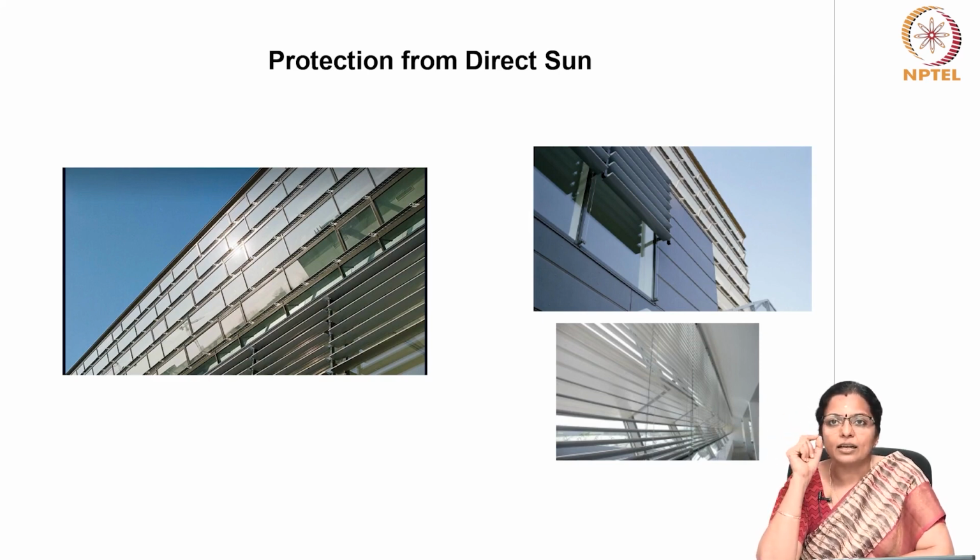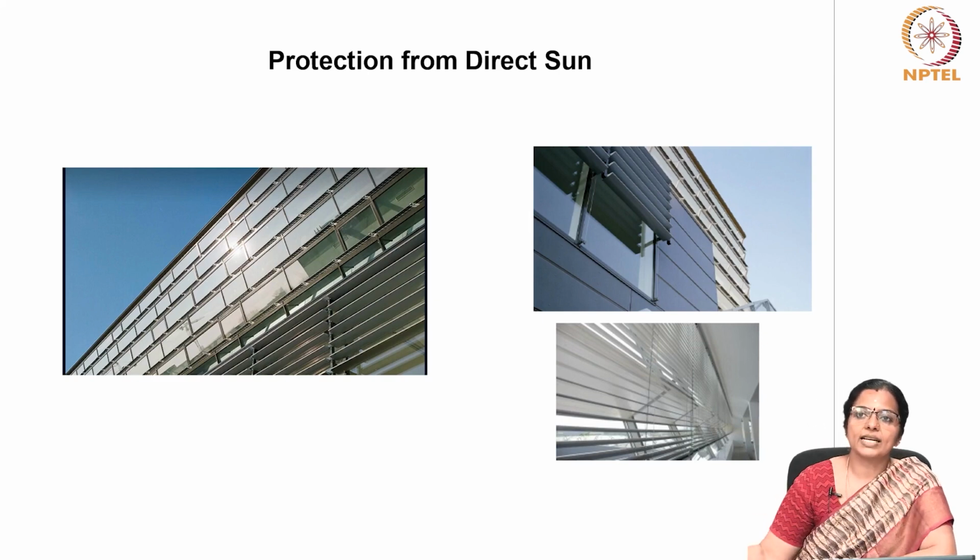The sunscreen, made of perforated lamellae, is located just behind the angled facade, and waste air from the entire story is vented at ceiling level. Because of this, heated air is drawn upwards behind the facade to the vents instead of spreading out into the space indoors. On sunny winter days, this air passes through a heat exchanger in which fresh air from outside is preheated.